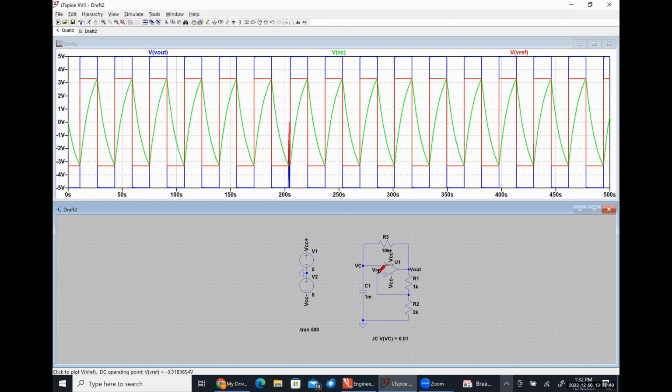VD1 is positive, VD2 is positive, and because both are positive, the output goes high. And in this last case, VN is 4.5 volts, which is greater than V high, and we see that the output is 0. So effectively, a window comparator works where if you're within the window, the output is high, and if you're outside of the window, the output is low.